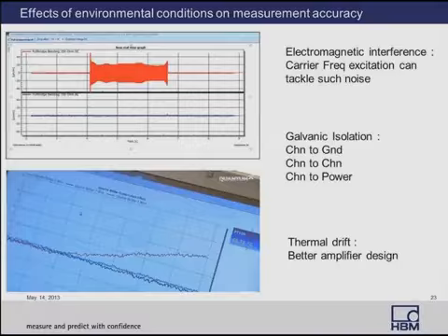Here's a view graph of how various noise and interference in your dyno applications affect your measurements. So the first one, as you see, is the red line, your actual signal. This is a strain signal over time. And when it sees some type of electromagnetic interference, look at the data, how noisy it is. Compare that to the signal. It is 20 to 40 times larger. So this data is unacceptable. And this interference may come in at any time unpredictably, that you have not much control on in many cases.